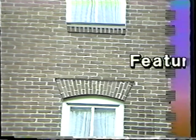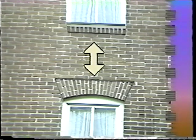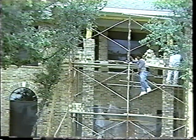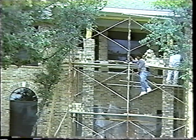The arch must have several features in order to work properly. It must have sufficient height of masonry above the opening. The ring must be of sufficient thickness. A rowlock course is usually adequate. And there must be sufficient masonry at the ends of the arch to resist horizontal thrusts from the arch. In residential construction, the most common problem is too little masonry to resist the arch thrusts.